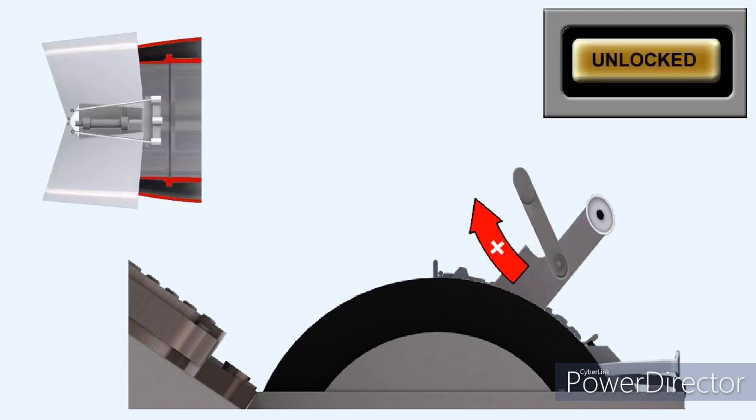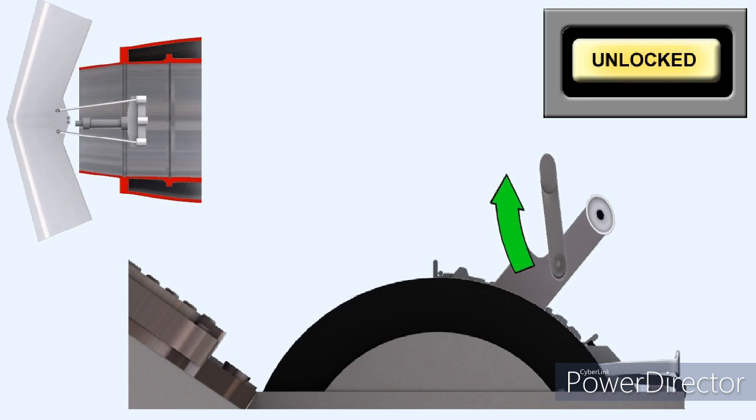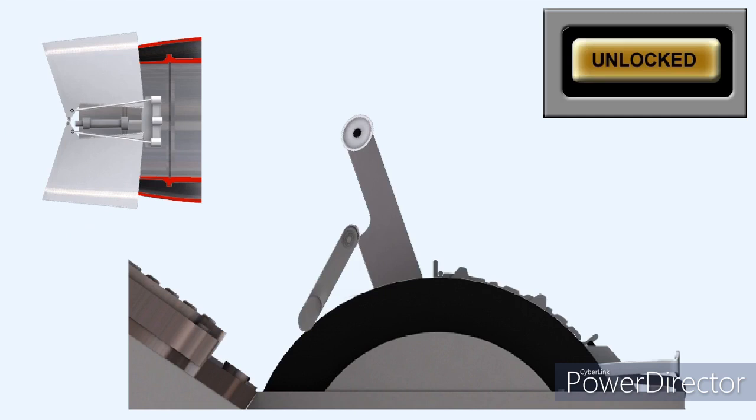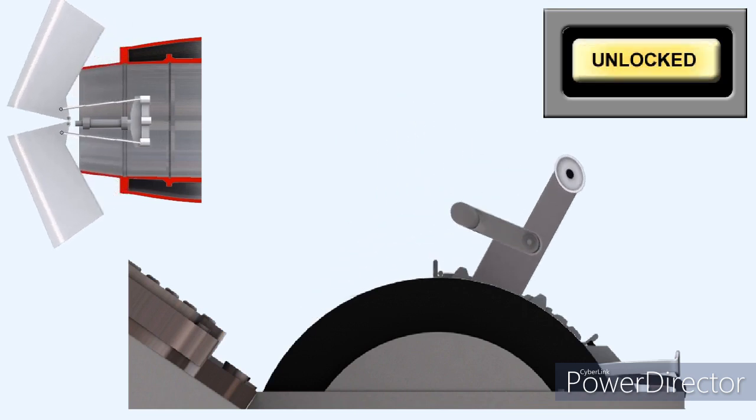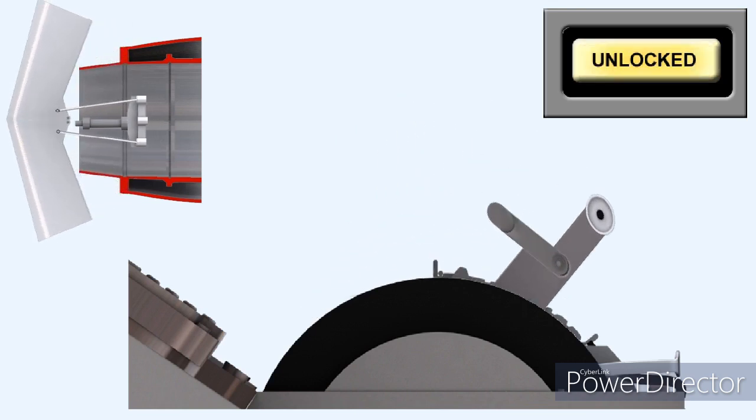With reverse thrust selected, engine power cannot be increased above idle power until the reverse thrust doors are in the deployed reverse thrust position. If, while forward thrust is selected, the reverser doors inadvertently move to the deployed reverse thrust position, the throttle will automatically close to idle.